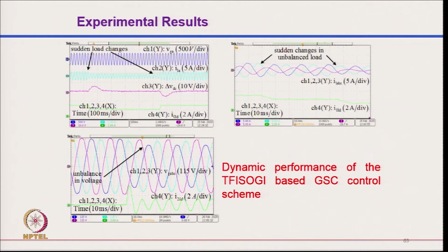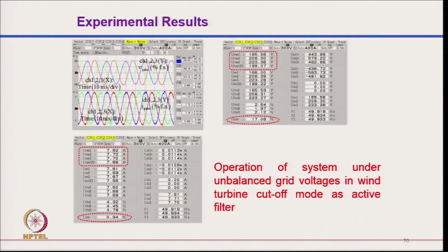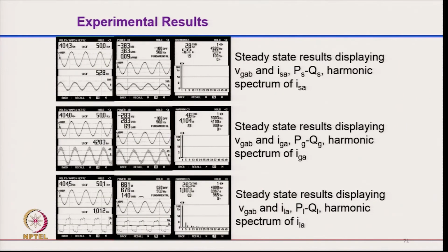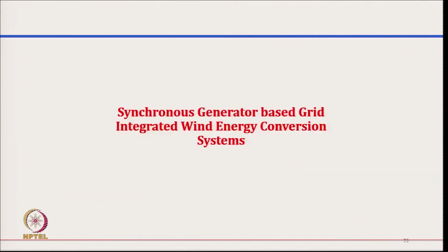This is the sudden change of the load, showing how the complete system changes corresponding to that. These are the 3 phase voltages and currents, and the total harmonic distortion in the current is typically less than 5%, on the grid side where the load current is quite high, on the order of 26% or so. So, that is about the DFIG.